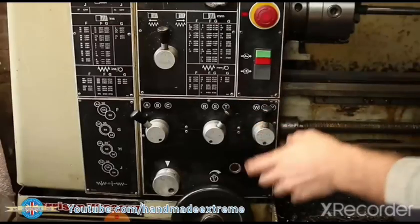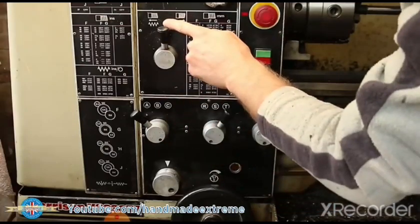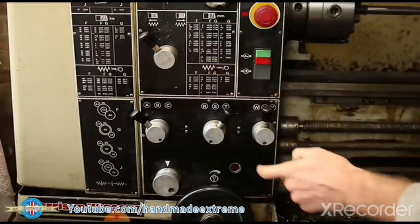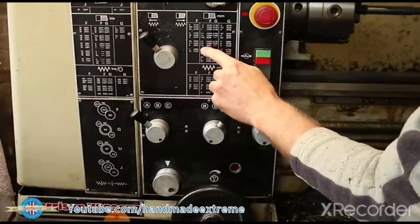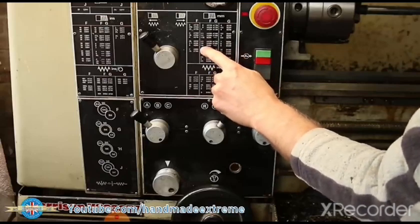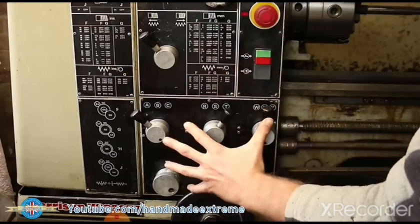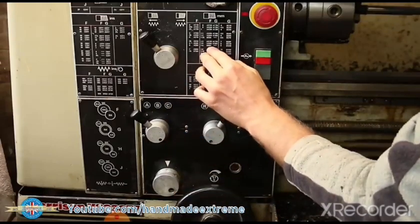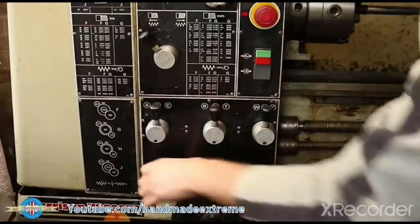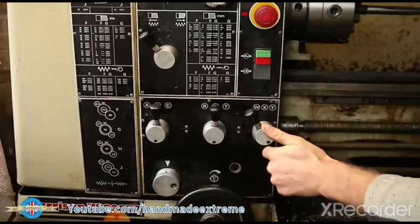Next thing to set up is the threading gearbox. We want the lead screw to be cutting a right-hand thread towards the chuck, and we need to look up the thread pitch on the lookup table here. This is an M14 by 1.5, so 1.5 pitch. That tells me that the selected set here needs to be BS6W.